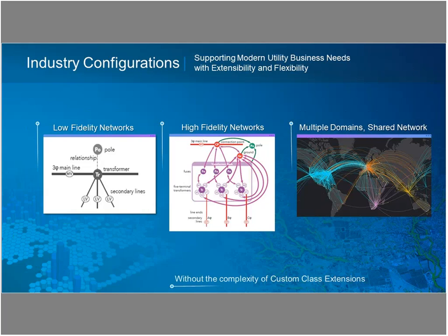Most gas, water, and even modest electric utilities will see massive benefits from a utility network with a low fidelity model. But if you have the need for custom or complex connection logic, like what you might find in a CIM model, the common information model, or if you're looking for a closer fit to a power systems model, you can actually manage your GIS network model to that level of precision. The diagram in the middle of this slide is an example of a move towards a more high fidelity model, when all of the distinct connection points and details within a transformer are able to be modeled with their connections relative to each other managed.